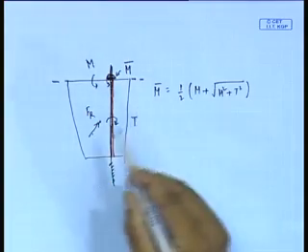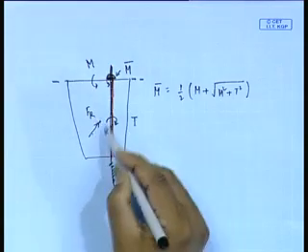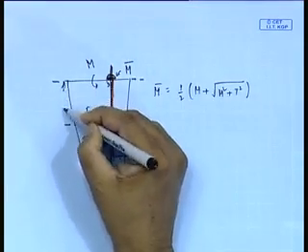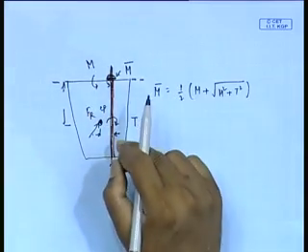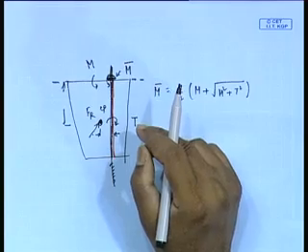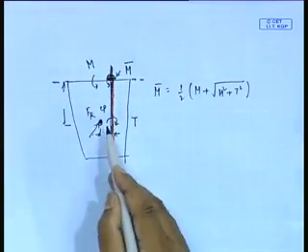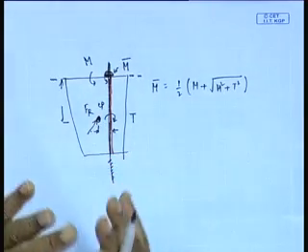So, in order to do that, what I need to do is to estimate Fr. Once I know the Fr, and of course I have to also estimate these distances, that is, this is my center of pressure Cp. I need to know the location of Cp, the formulas for this Cp I will come to later on. Once you know that, you can find out the moment coming, and of course once you know Fr, you can also resolve these forces as we mentioned yesterday, how you can determine Y dr, N dr, etc. There are hull properties.